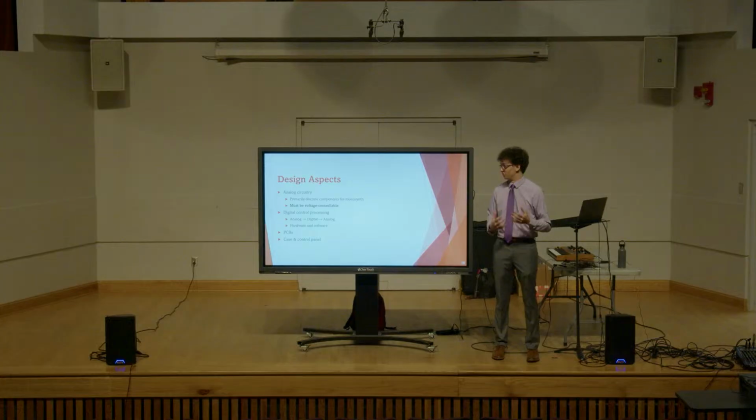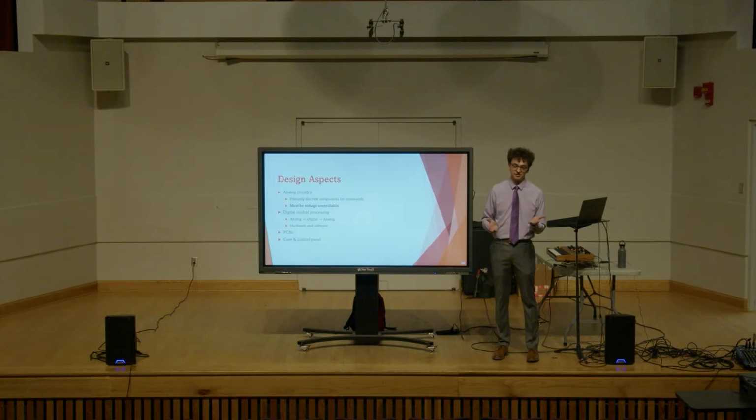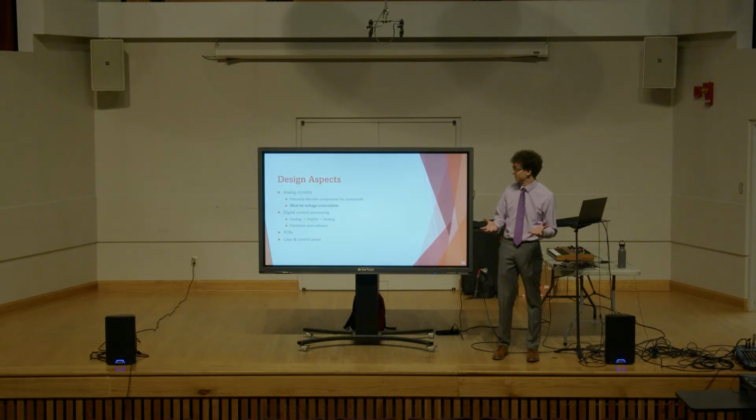So the main aspects of this project are analog circuitry design, and as I mentioned before, primarily discrete components. And unfortunately, well, not unfortunately, this is really cool, but unfortunately for what I had done the last time I gave this presentation, every single parameter that I'd like to control for this synthesizer must be voltage controllable because I want to store presets. So I can't have a potentiometer or an analog switch built into a circuit, because that won't change instantaneously with the push of a button or a turn of a preset knob. That is a reliance on a set fixed analog device. I can't have that on a preset synthesizer.